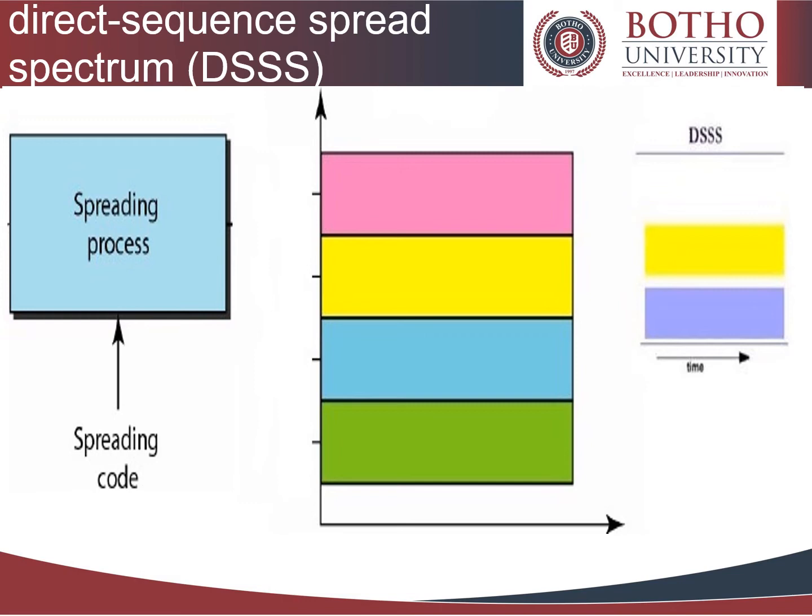It replaces each data bit with n bits using a spreading code. The spreading of the information is performed by using a spreading signal called the code signal. The code signal is independent of the data and is of a much higher chip rate than the data signal.